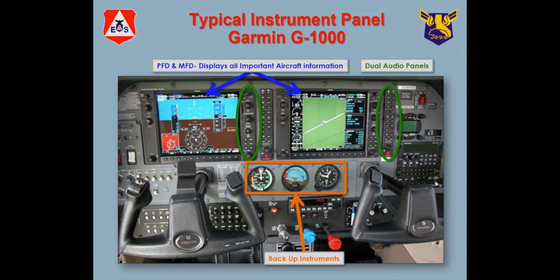So if you're flying and you can't see outside the cockpit, you use a device like that to replicate the horizon so you can tell whether the airplane is turning right or left, if it's level, if it's climbing, if it's descending. And then finally, your altimeter. It's important to know how far you're above the ground, because if you're 800 feet above the ground and there's something in front of you or around you that's 1,000 feet above the ground, you're going to own a piece of the rock. So it's important to know how far you are up in the air.